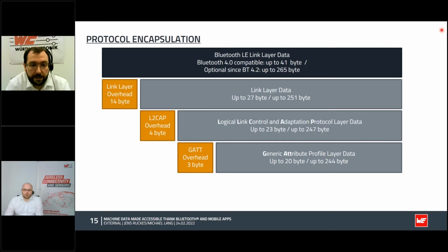So the general thing is, Bluetooth Low Energy, as Michael introduced in the very beginning, was introduced with version 4.0. In the meantime, we are at 5.3. So what happened? Pretty much all additional features that came in are optional. So you need to consider your target application, and this includes the cell phones that should be used. We have 2 main cell phone manufacturers, using Android or Apple devices, and both of them have dedicated sets of functions, rules and recommendations to work the best.